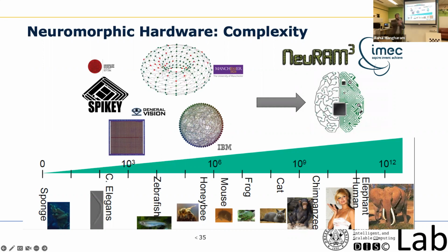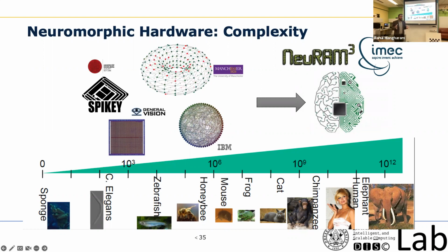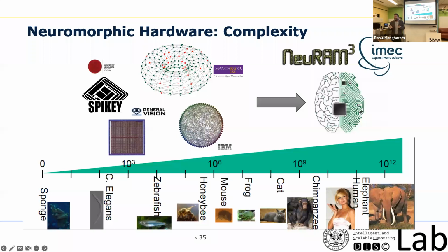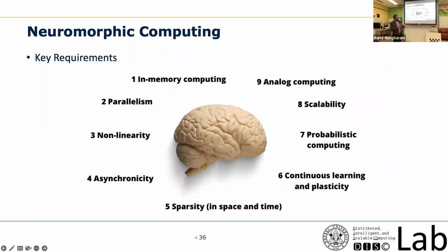And with 1 million neurons and 10 billion synapses, the energy consumption can be exceptionally high. So we have to be very, very careful. In our recent work, we have shown that out of all the energy consumption of a neuromorphic hardware, the communication constitutes almost 60% of the energy. 40% of the energy is consumed in the computations of the neurons. 60% is on the interconnect.